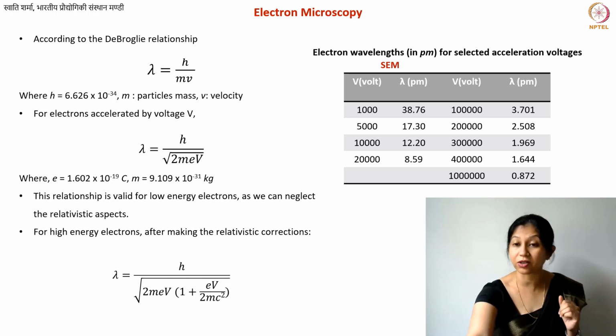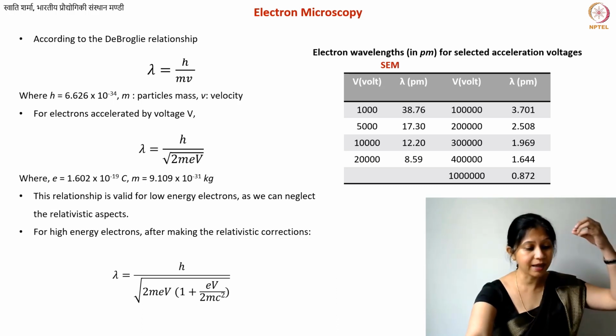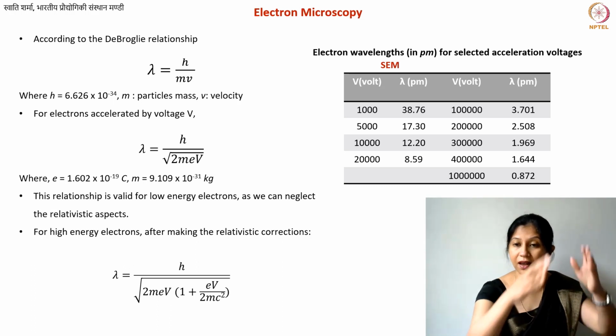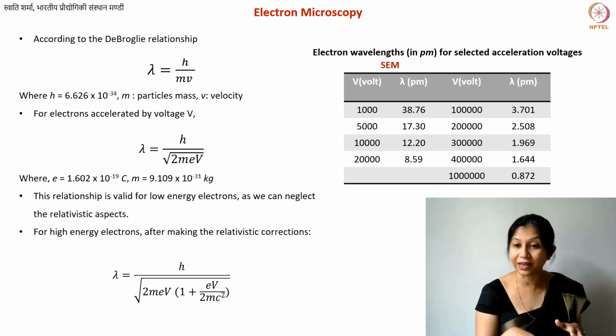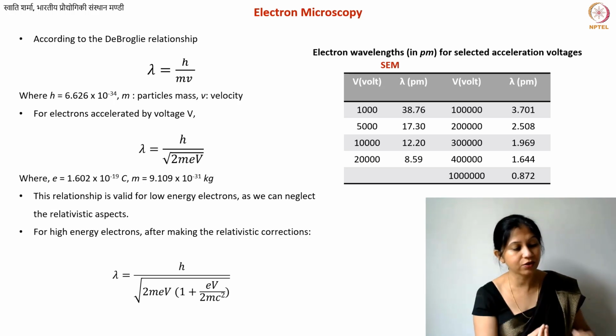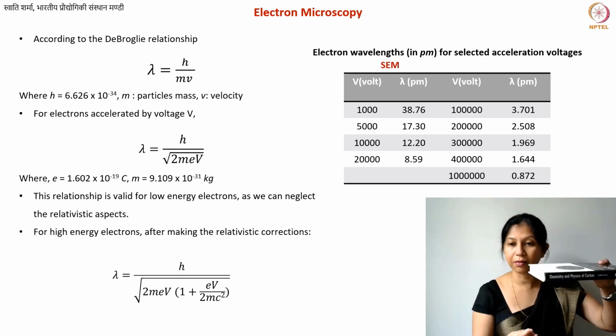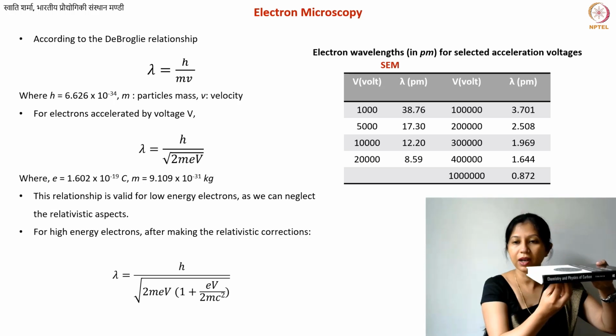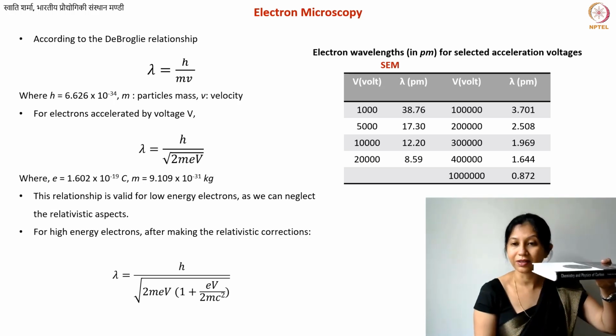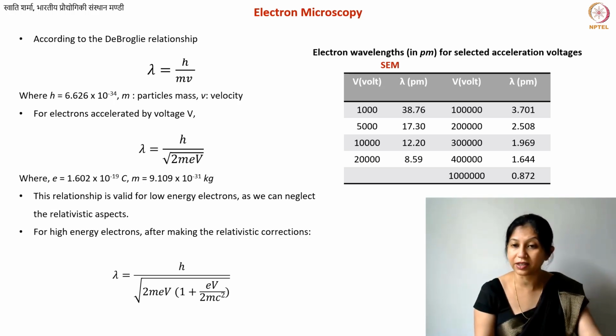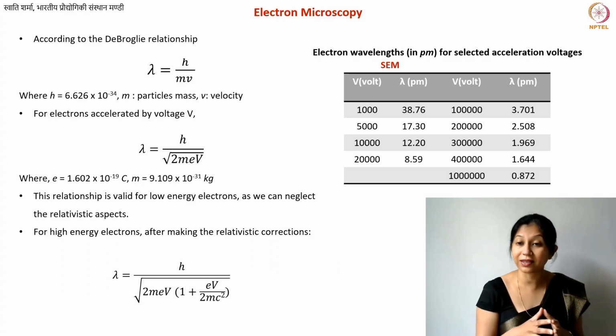Scanning electron microscopy we are not going to cover in this lecture, but it is something which maps your surface. That is just taking the image of the structures of your surface, but not going through your material. Transmission, as the name suggests, means there is some sort of transmission of these wavelengths through your material. They are transmitting and we are collecting. This is your sample, the electron comes from here and goes through your sample, and comes out with the loss of some energy also.